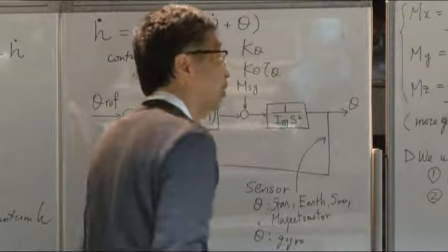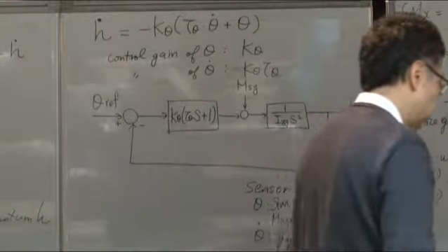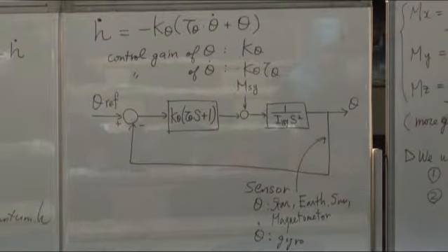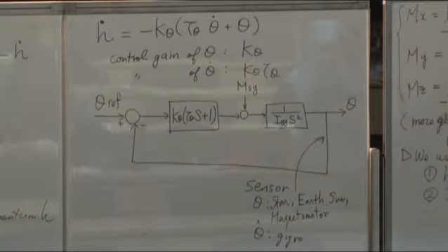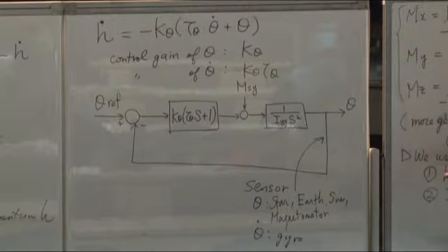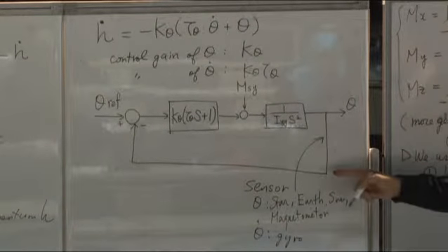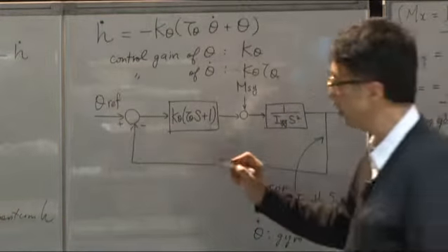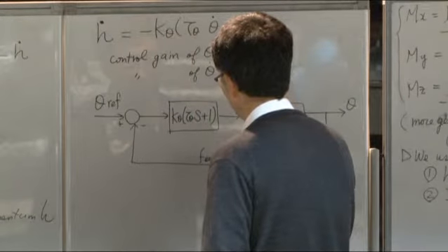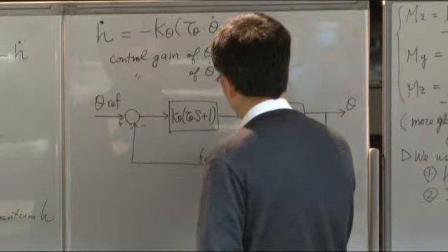There are several types of gyro, such as a tuned dry gyro, which is a mechanical gyro, but recently we are using the fiber optical gyro, or such kinds of optical gyros. In any case, theta and theta dot are measured here, and go into the feedback loop. So this is called the feedback loop.